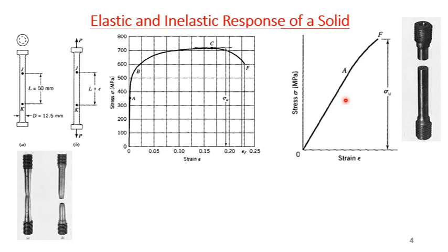This is a stress-strain curve under a uniaxial tensile test of a brittle material. There is no yielding. Now, if you look at the fracture, it is perpendicular to the axis of the member, meaning it fails under normal stresses. Whereas for a ductile material, the failure is cup and cone, approximately 45 degrees, meaning it fails under shear stresses, where the shear stress is maximum.